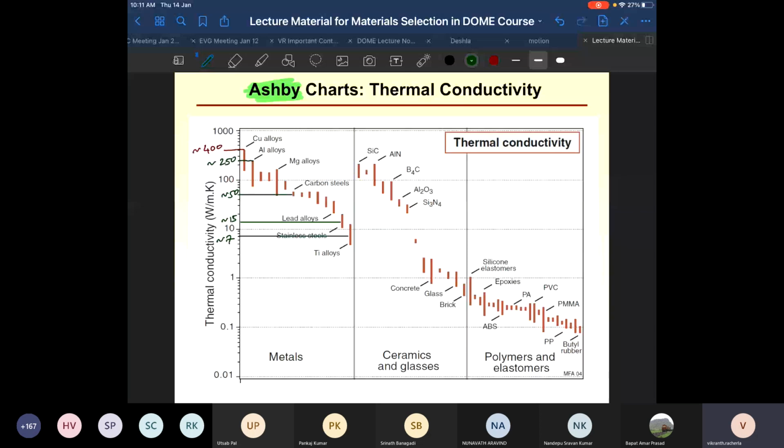If you look at the thermal conductivity of titanium, it is about 50 times smaller than that of copper. So it has very low thermal conductivity, and this has implications. Can you name some particular problems that you face while handling titanium because of this very low thermal conductivity?